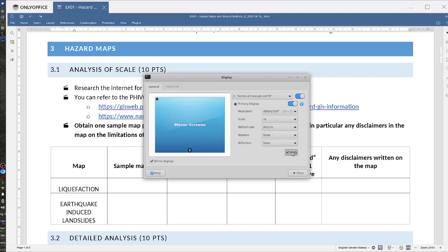Yeah, but the problem with deterministic is that the values are too big. The advantage in probabilistic is you get the best approximate. I mean, you factor in all the earthquakes in the area. You consider their likelihoods, and you can consider all the scenarios, and you get one number that approximately represents the most likely condition that will be encountered by the project.